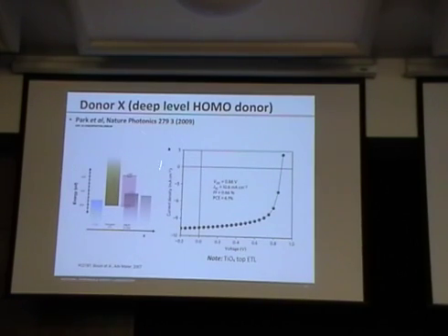Okay, so the idea was that we want to harvest holes out of this transparent contact electrode pair, right? So that means we want to pull holes out of the polymer. So we want there to be no energy differences here, or at least we want to minimize those energy differences so that we ease the transport out. At the same time, we don't want electrons going into that contact.